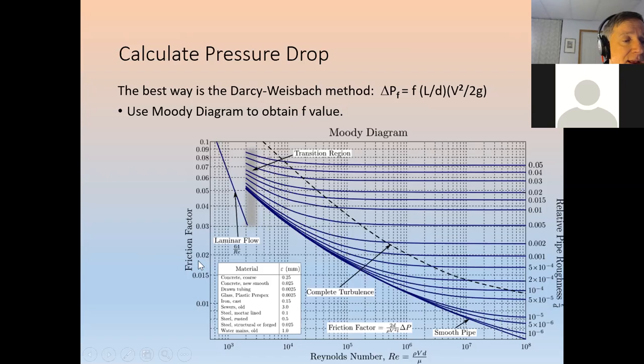And then you see in this Moody diagram, it's a bit busy, but you have a laminar side on the left, laminar flow, and turbulent flow on the right. So on the x-axis, you have Reynolds number, which we talked a lot about. This gray area is this transitional area between laminar and turbulent flow, starting at about 2000. And Reynolds number, Mach number, Weber number, all these are dimensionless units. They have no dimensions. And then the friction factor is up here. So you might say, well, laminar is evil. It's horrible. Look how high the friction rate is.